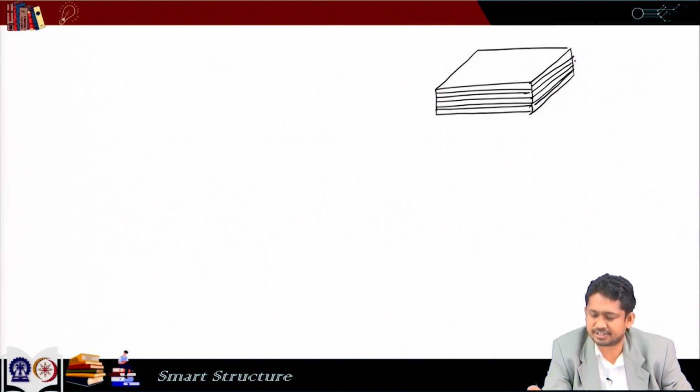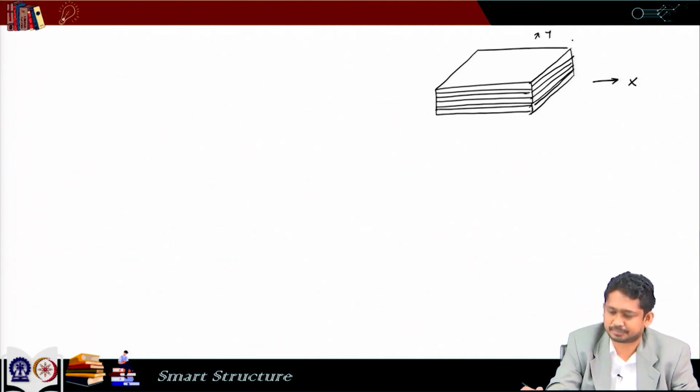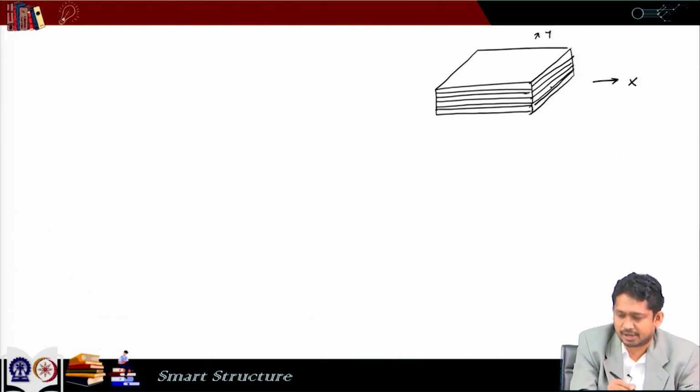We know their stress strain relation with respect to their own fiber orientation direction and with respect to a global x y direction as well. So, now today we will integrate the quantities along the thickness of the laminate, and we will relate the stress resultants in terms of the strain components, and the strains are already related to the displacement components. So, finally, it would relate the stress resultants with respect to the displacement components.